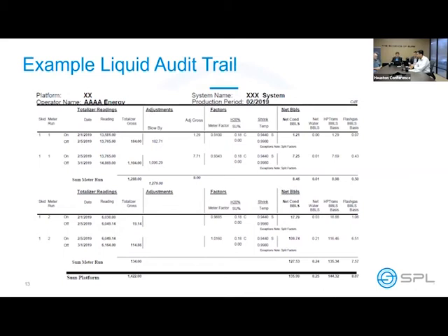So another question: how do you allocate fluids when the composition is unavailable in a commingled system situation? When the composition is unavailable, this is when we would use the physical shrinkage calculations that we did in the field or in the laboratory. We certainly have physical shrinkage calculations. Oh, absolutely. I didn't think about it.